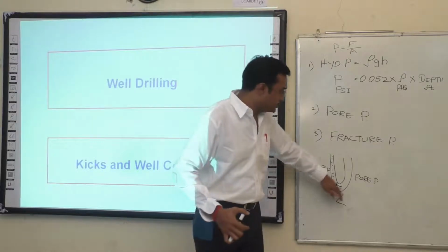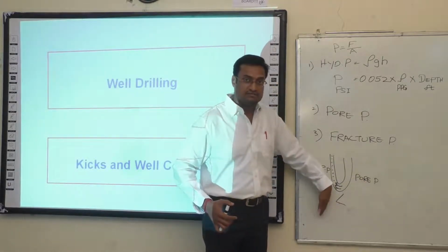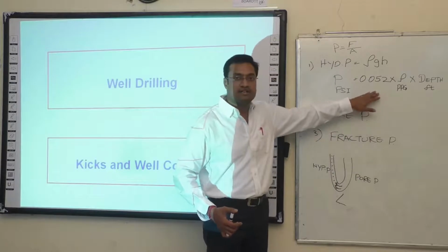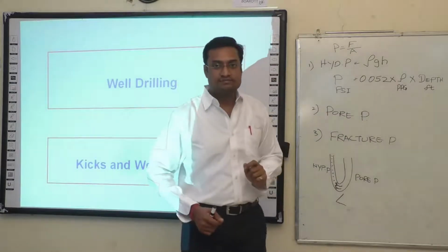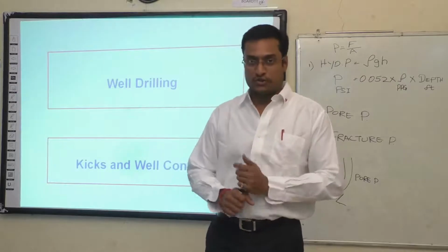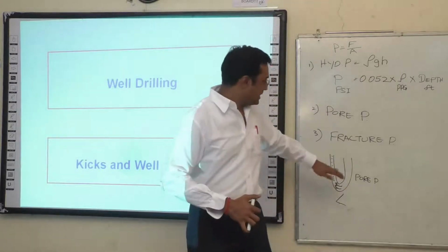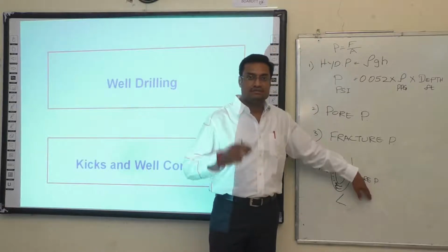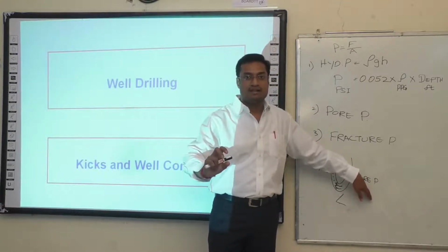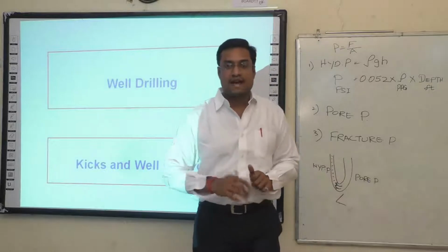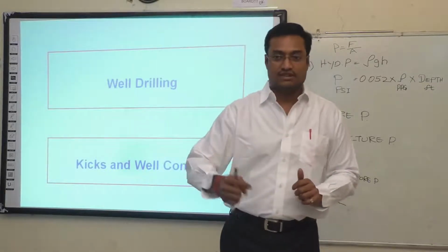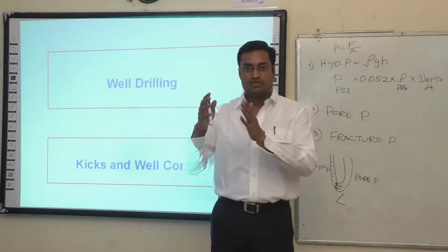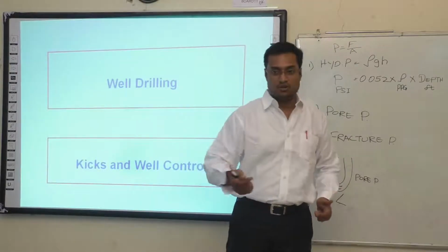If the well goes into underbalance condition, which means the pore pressure is more than the hydrostatic pressure, we have to stop drilling and do the well control procedures to make sure the hydrostatic pressure becomes more than the pore pressure. So we have controlled the well, confirm it is safe, and then we proceed with drilling. This is well control.